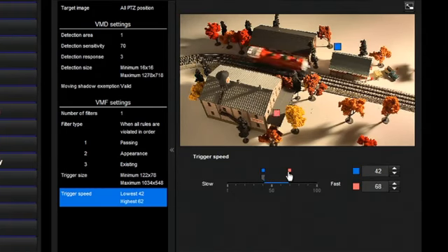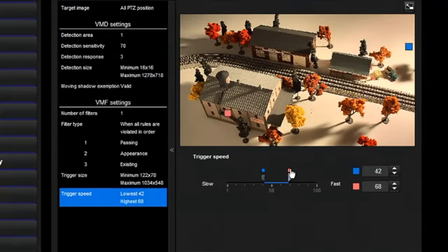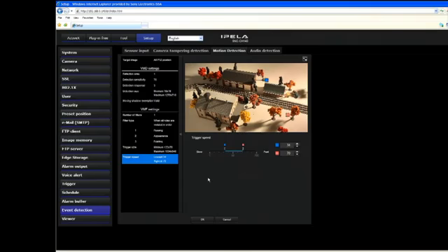The DEPA Advanced enabled cameras give you a useful setup tool to gauge speed, as it can be difficult to estimate speed based on a pixel per second number. In this case, we have set up the passing filter to trigger on objects moving faster than the blue dot and slower than the pink dot. In other words, triggered between the low and high thresholds in pixels per second.